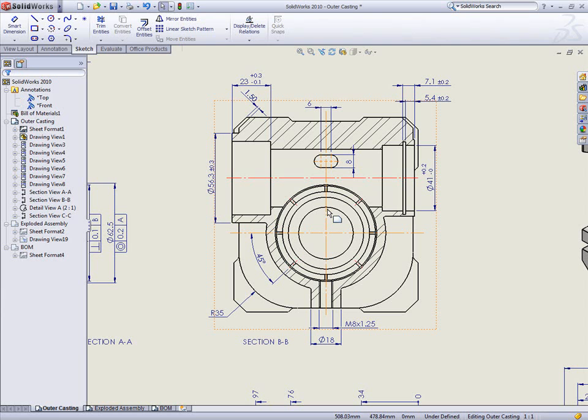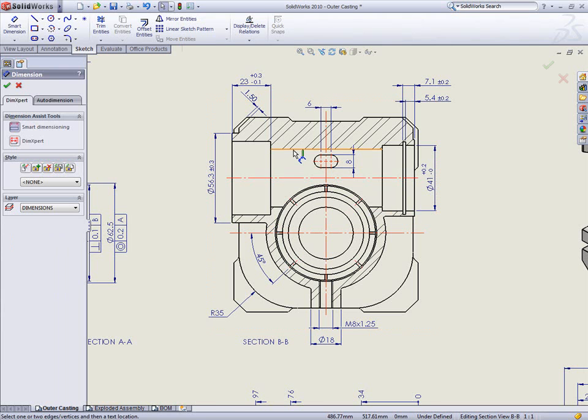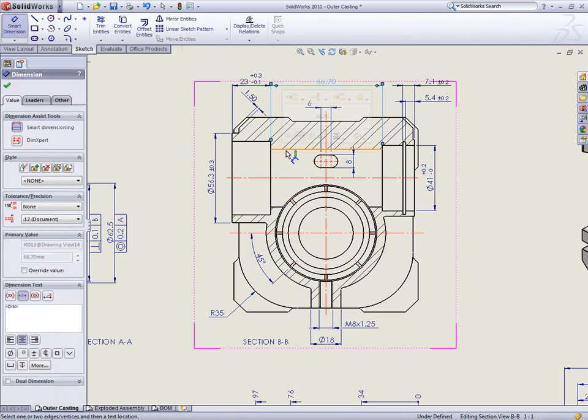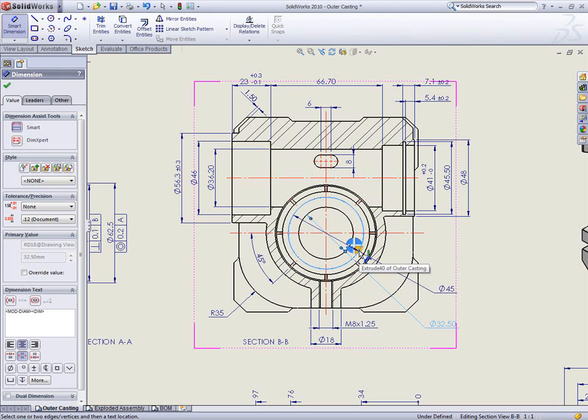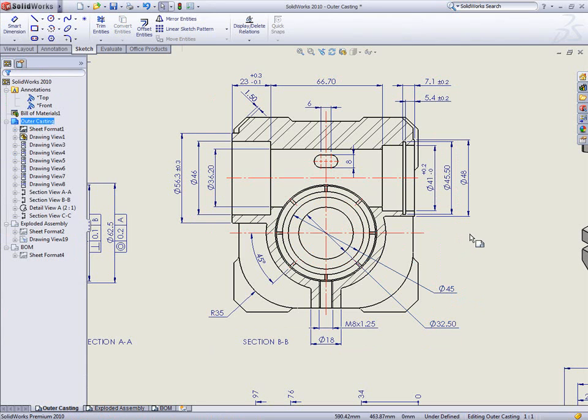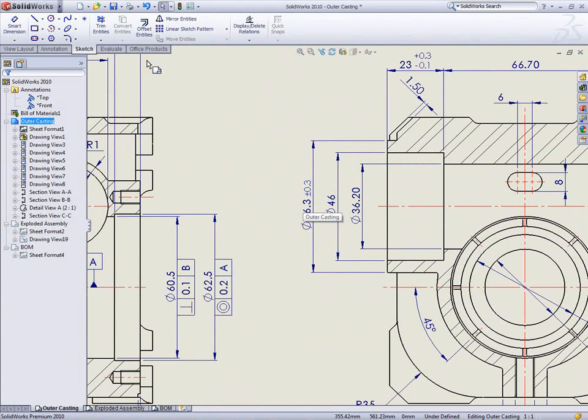Now when adding dimensions, you can add rapid dimensions by using the little pop-up widget. A simple mouse gesture places the dimension either side of the drawing view. Dimensions that stack up are automatically moved to make way for the new ones and to ensure none of them overlap. Each dimension is placed with minimum effort, making an easy-to-read drawing fast. Notice also that cylindrical dimensions added on a section now get their diameter symbol automatically.